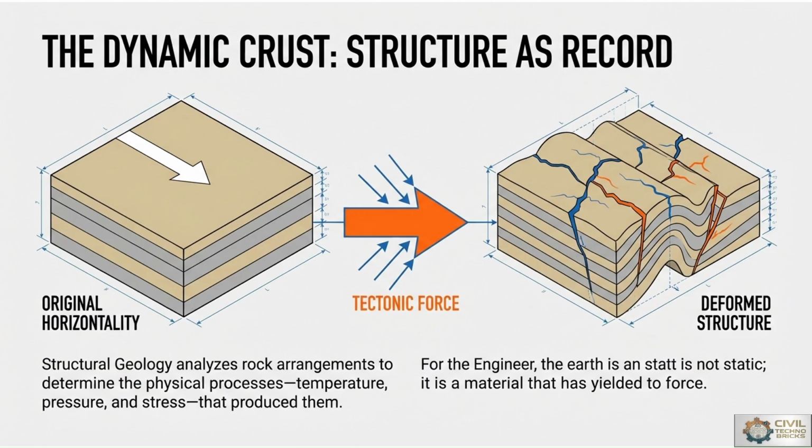The displaced zone becomes structurally weak and contains crushed rock material known as fault gouge. From the civil engineering point of view, these fault zones are highly important because they reduce rock strength, increase seepage, and may trigger seismic instability near engineering structures.